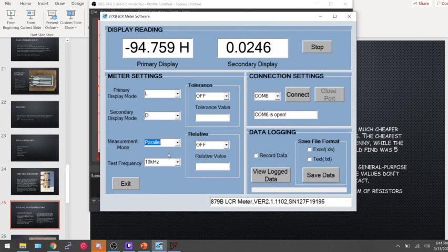Now let's take one of my wire wound resistors, and I will show you what I mean. These wire wound resistors are very susceptible to inductance. That's better. So as you can see, it's essentially the same as having a 3.7 microhenry inductor in your circuit that you're not accounting for, which can be very bad.